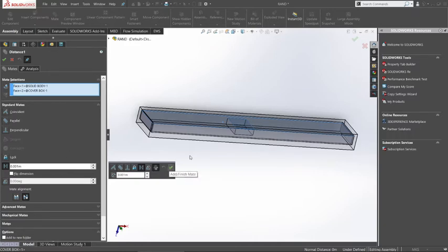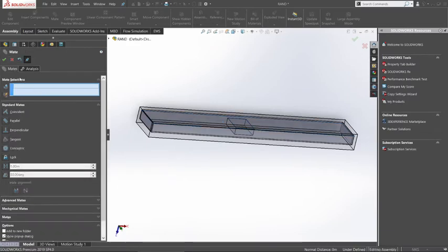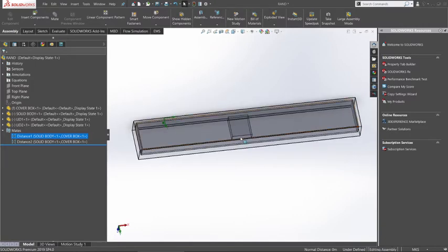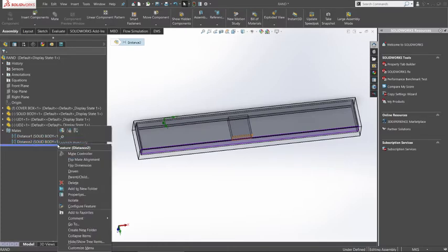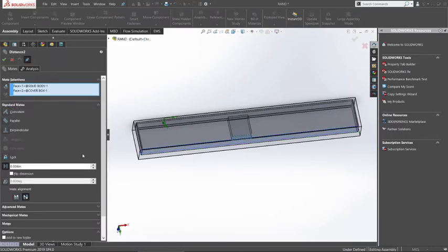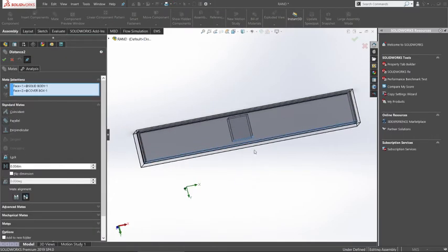This is what I have done first for this one, but that does not tell me where I should put this one with respect to the other ones. So I have to choose another mate, which is this one, solid body, and this is telling me that the gap between the lateral surface of this one and the lateral surface of the duct should have a distance between them, which is also, I think, somewhere around 0.004, because it is larger in space.